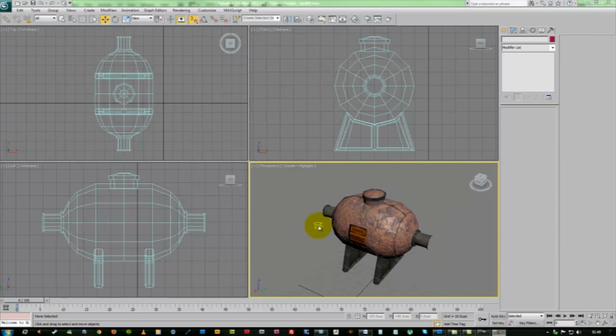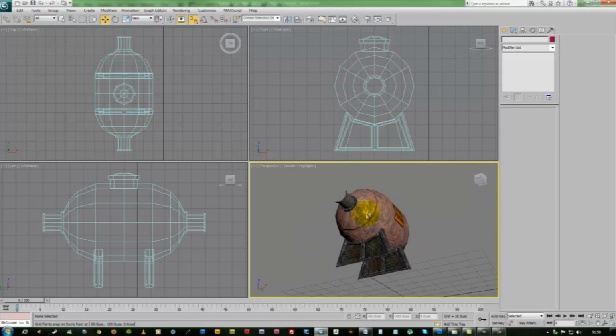Now we have our model, it is important to double check all the information due to problems which could arise later on, as mistakes made during this process are not as easily repaired after this stage, especially if you are creating lots of modular objects. The other main points that need to be checked are sizes of the asset, naming conventions, and the original position and orientation of the asset. Firstly, we need to make sure it is positioned and aligned correctly.